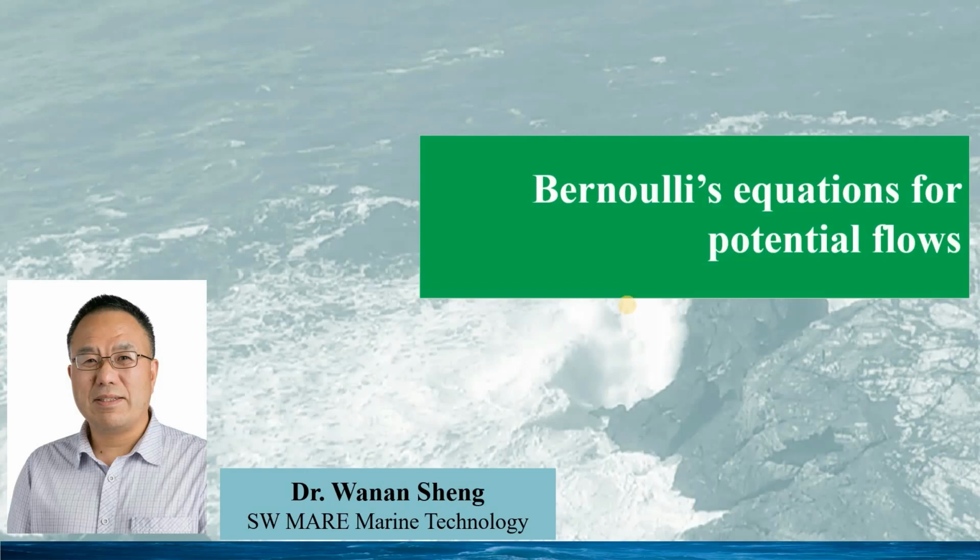Thus, we will show the Bernoulli's equations for the compressible flows under the assumption of an ideal gas for the air. This is generally accepted for engineering applications. In addition, a more useful relation would be derived for the flow past thin airfoils at small angles of attack. Thus, the famous Prandtl-Glauert compressibility correction can be derived.